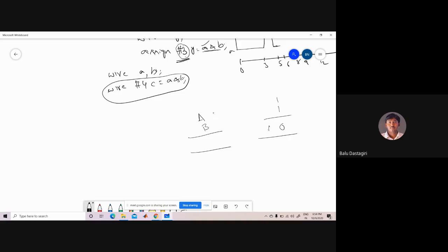But when you are declaring it in the data flow, for example C is equal to A plus B, I am adding the 2 numbers A and B, but the output here is 2 bits. I declared the inputs as single bits, so I cannot assign a 2-bit result to C directly, because it is a sum and it is a carry. So I cannot assign C is equal to A plus B directly.